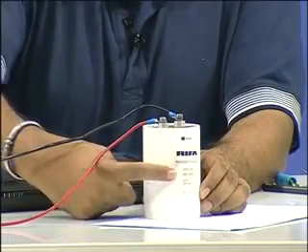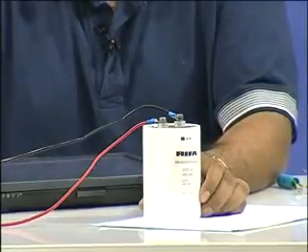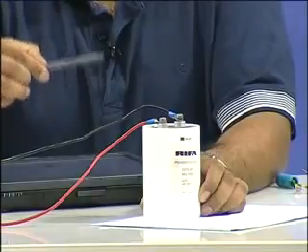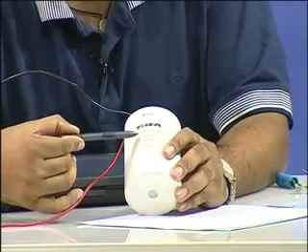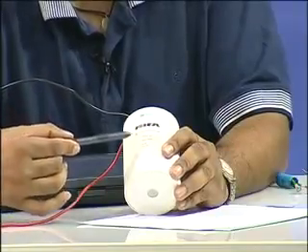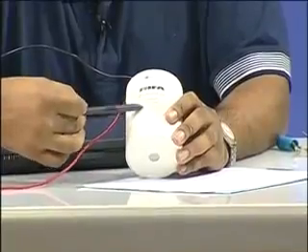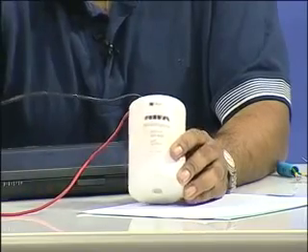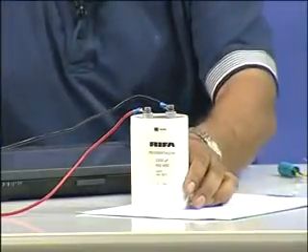And here you will see the values written, the two main values which we keep looking at in a capacitor, which are the capacitance value and the voltage withstanding capability. So, if you see in this, it is a 2200 microfarad capacitor and it can withstand up to 450 volts DC. Okay. And these are other numbers which you will find which indicate the tolerance values. It can go from minus 50% to plus 100%, so on and so forth. Depends upon the capacitor and the make of the capacitor and things like that.